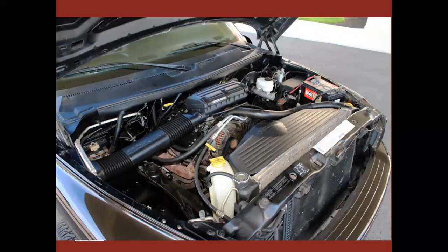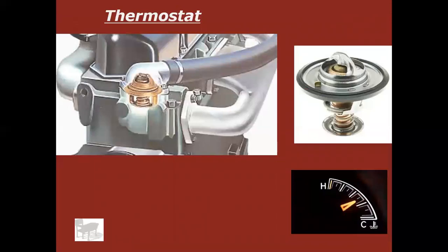Another example of a cross flow. Notice the antifreeze tank, or kind of vault of antifreeze, plastic over here. There's your radiator, real wide, real long. There's the outlet from the water pump. So it actually pushes it into here, fills that plastic up on that side, and then pushes it through this aluminum over to here, and then goes back in the engine. Cross flow. Okay, thermostat. Let's talk about the thermostat.